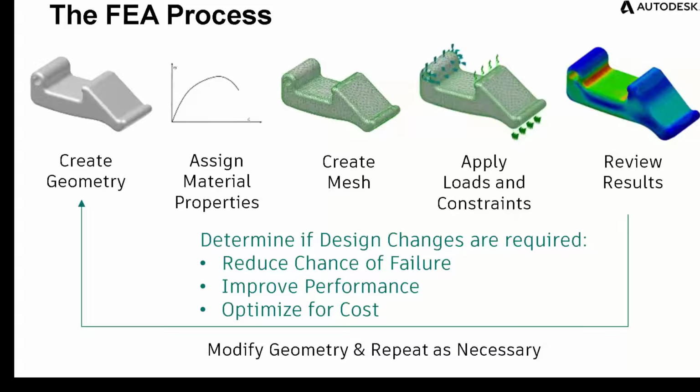That's creating your mesh, or your net, as a lot of people call it. The mesh can really help you identify and zero in on where a problem might be. A mesh that's too generic or too coarse won't necessarily show enough detail for you to say, okay, the problem is in this confined area. It might be too widespread. For that matter, it could even be calculated in another location. So you have to refine your mesh, tweak it down, get smaller meshes, and even do local mesh control to zero in on exactly where that problem might be.